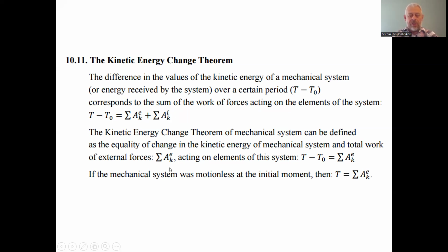The kinetic energy change theorem of a mechanical system can be defined as the equality of the change in the kinetic energy of the mechanical system and the total work of external forces acting on the elements of the system. Yes, this is in the case if we do not consider the internal forces, as is characteristic for the rigid body. For the elastic body, we have to account as well for the action of the internal forces.